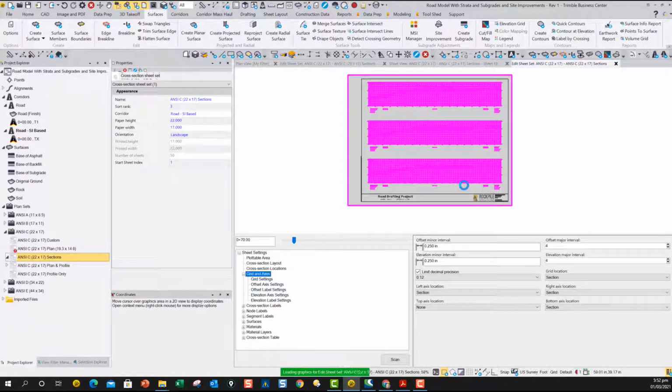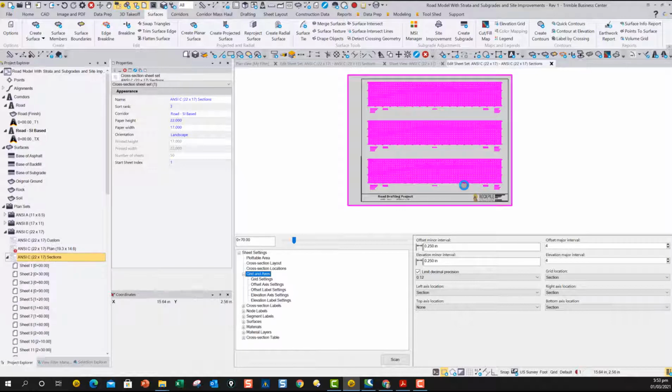But I think in general, if you break the finish grade model up in the right way to get your subgrade shapes the right shape, then as long as you've got the 3D strings to apply those pavement stacks, you can actually do that. Okay, the only area that you would have an issue is under curb line, actually, because curb has got an irregular shape at the top and you can't use site improvements to apply that. So the way you would have to do that would be to create basically a rectangular block for the curb, which isn't ideal. And I'm sure we could work around it somehow, but haven't had time to think through that too much. But anyway, in general, the site improvements for the pavement can be applied this way.